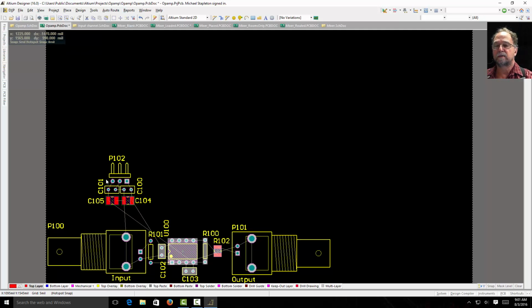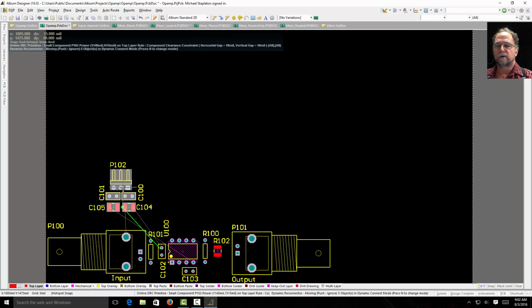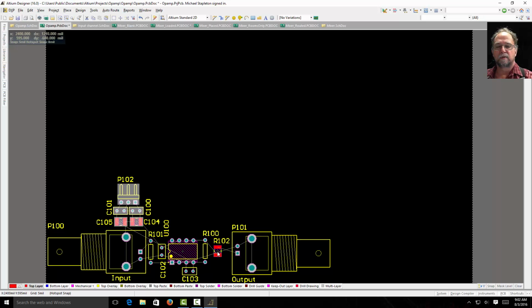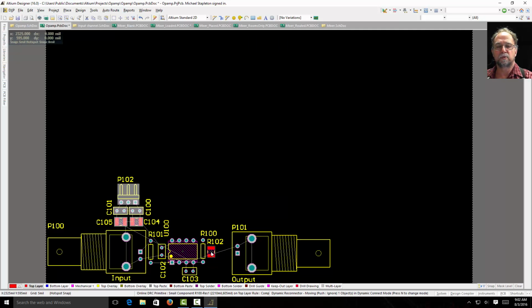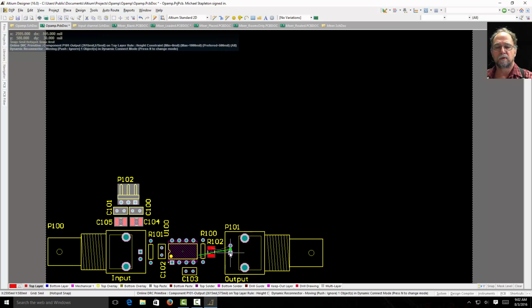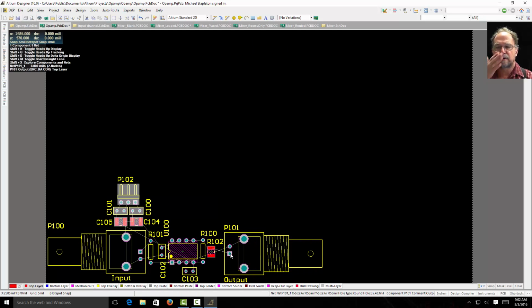So think about it. You want to make this thing as efficient as possible without making your life too hard that you won't be able to put your parts in or work on them. All right, I'll move this down a little bit. Let's see, I can probably move these resistors a little bit closer. Don't go too close, they'll turn green, right? Green's warning me I'm too close. All right, so there's a rough shape for a layout.